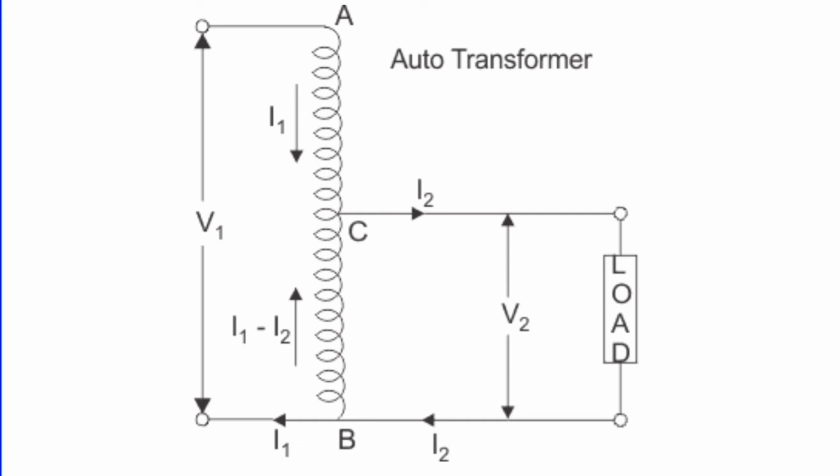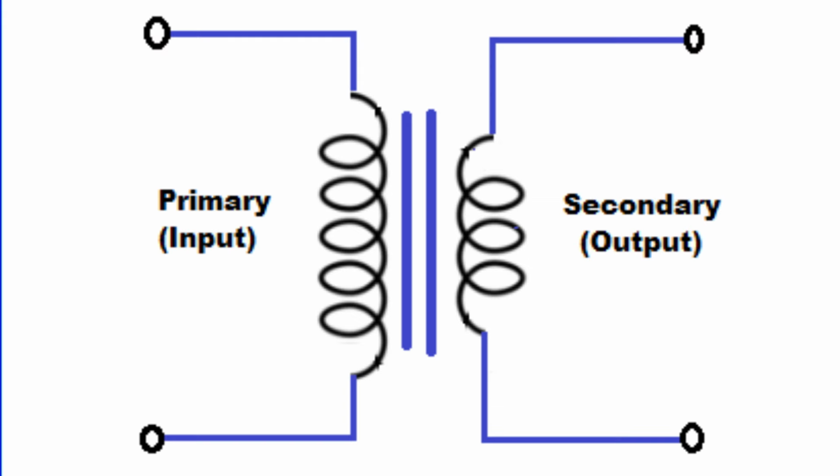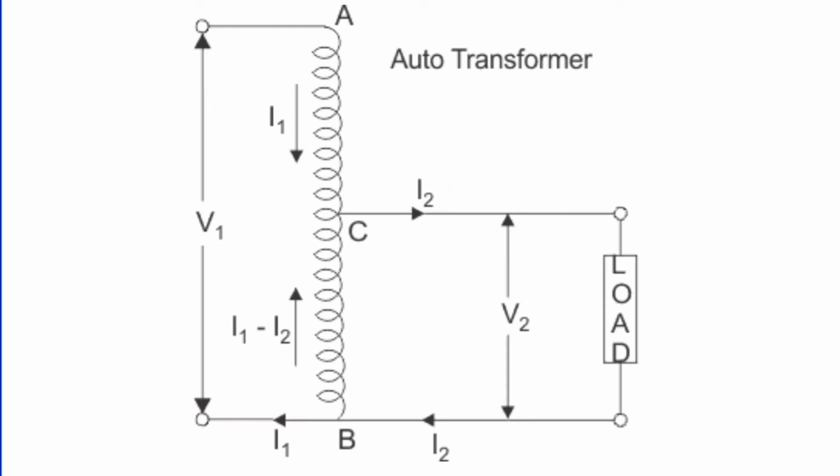The primary difference lies in the way the primary and secondary windings of the transformer interrelate. In an autotransformer, a single winding is used both as a primary and a secondary winding, while a two-winding transformer uses two separate windings for these purposes. Imagine a winding AB with total turns N1. This is the primary winding. Now picture a tap from point C on this winding. The portion BC now becomes the secondary winding.